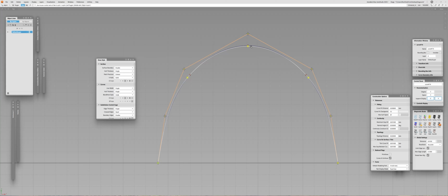So for example, you want to keep continuity between one piece and another piece. Because of the curvature, the way the edit points spread to follow the geometry, it accommodates the geometry, but at the same time the values may be floating, and the distances between the edit points at the point of connection can be too short or too long, and it will be difficult to maintain curvature if you want to align it to something else. In uniform, this is not the case.